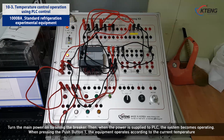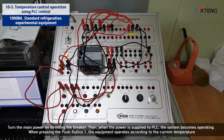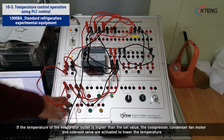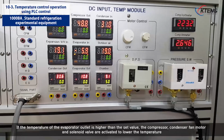When pressing the push button 1, the equipment operates according to the current temperature. If the temperature of the evaporator outlet is higher than the set value, the compressor, condenser fan motor, and solenoid valve are activated to lower the temperature.